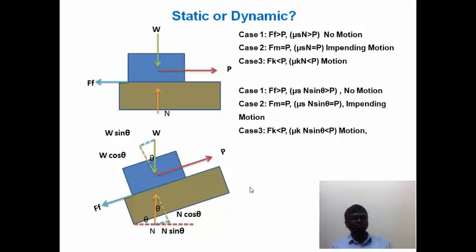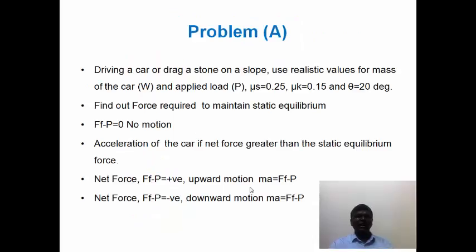When you incline, then you have to resolve the force. In this case, if the angle of the incline is theta, then you have to resolve the forces. That is, W resolved in the horizontal component is W sine theta, and the vertical component is W cos theta. The reaction force, similarly, you have to resolve it. Then you have to make the equilibrium balance, the equilibrium condition, and then you have to find out the various aspects of the forces involved in the cases. So we learned various kinetic and static friction conditions.